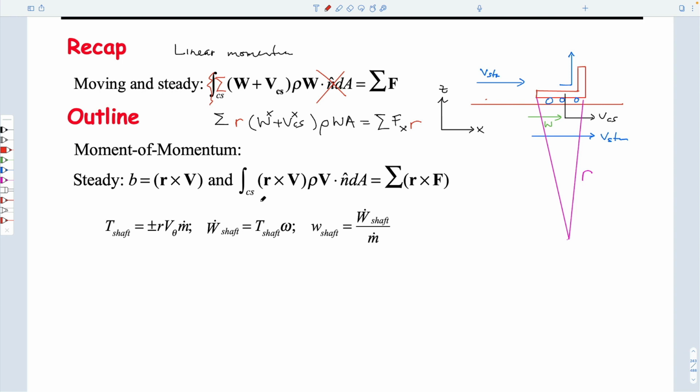And it turns out that the moment of momentum equation, rotational momentum instead of linear momentum, is exactly that. It looks a bit more complicated. Perhaps you can see a connection between Reynolds transport theorem done for the linear momentum with this. This is a rotational velocity that's been added, multiplied by some kind of velocity with all the other terms. And this is a rotational velocity multiplied by the force. It's probably not completely rigorous what we've done, but it serves to make the point that really it's not very different at all. And so we're going to do an example for the sprinkler that does that.